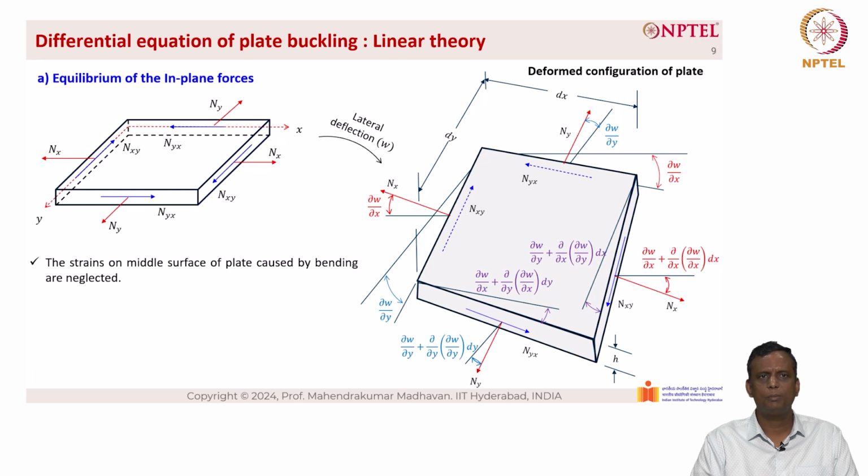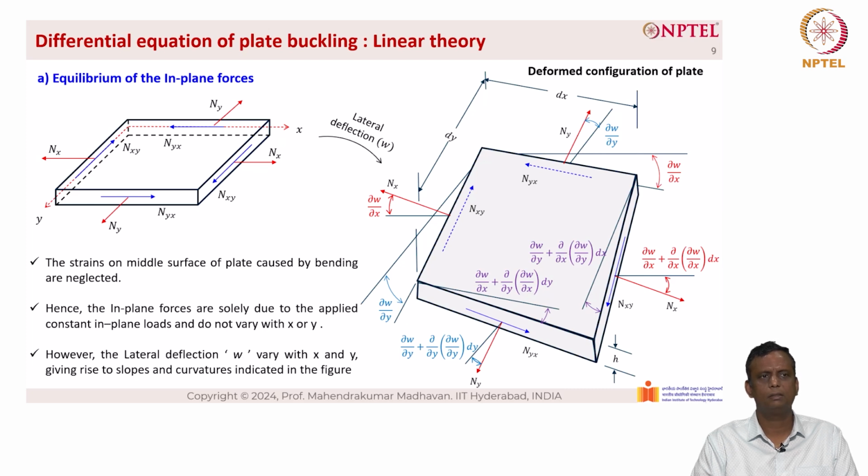Now, the strains on the middle surface of the plate caused by bending are neglected. Hence, the in-plane forces are solely due to the constant in-plane loads and do not vary with x or y. However, the lateral deflection W varies with x and y, giving rise to slopes and curvatures as indicated in the figure on the right hand side.